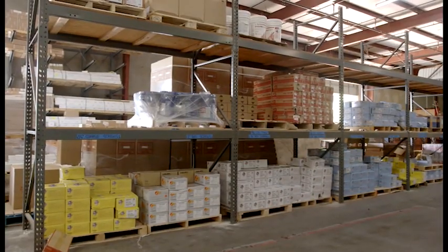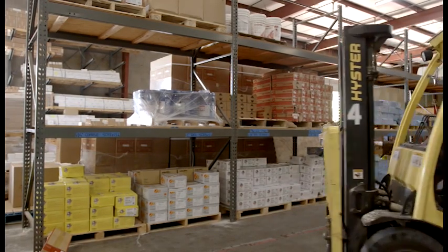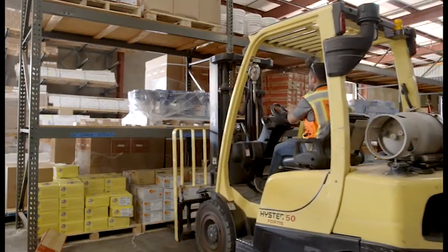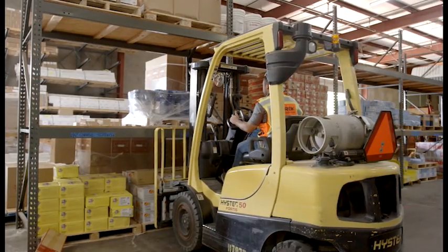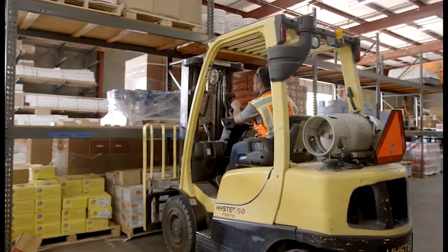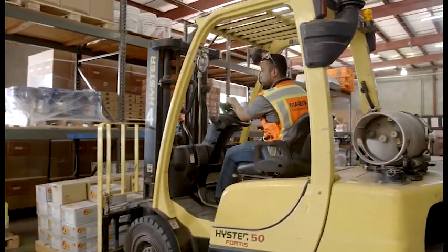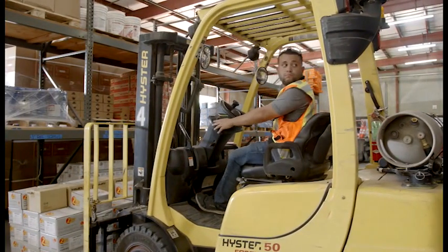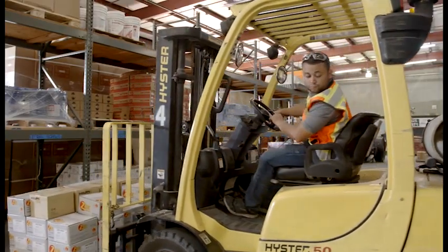Approach the load slowly and carefully, and make sure the truck is squarely in front of the load and the forks are set at the correct height. Forks should be placed under the load as far as possible, at least 2/3 the length of the load, and the mast tilted back carefully to stabilize the load. Carefully lift the load off the ground just enough to clear. Tilt the mast back slightly to rest the load against the backrest extension.